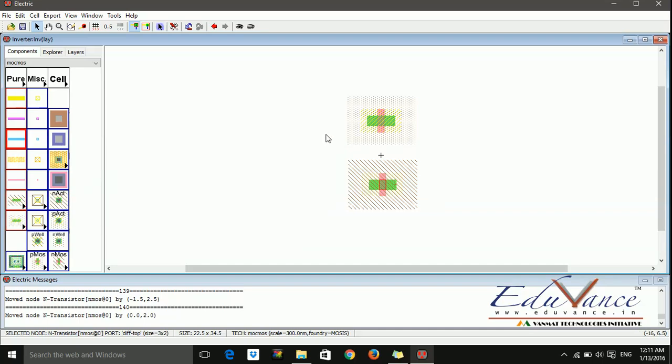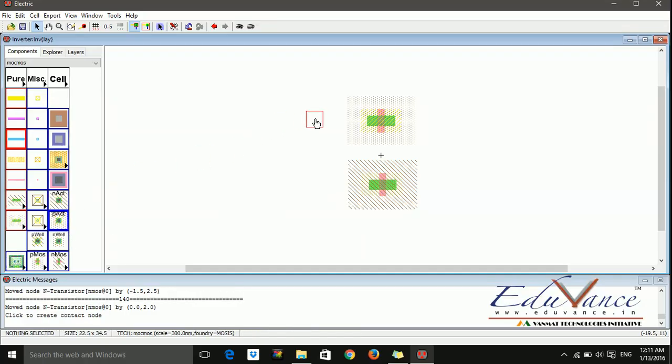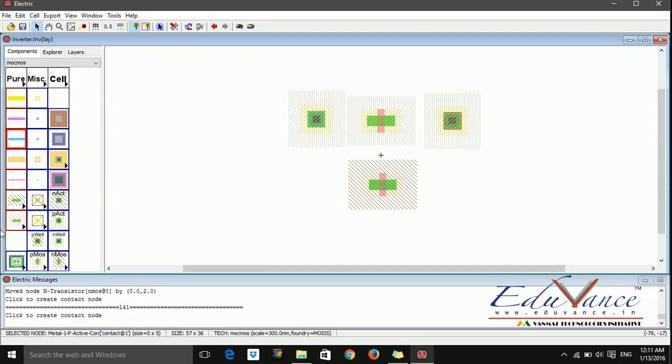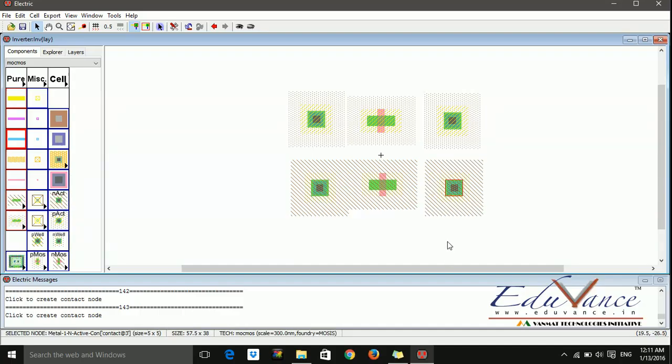Okay. Now we need to connect the drains and sources to each other. Now we can't make the connections directly. We'll need a contact. So we use the active regions. P active region is used for PMOS. So I click and click here. P active, N active, click and paste. Okay, so I have my regions in place.